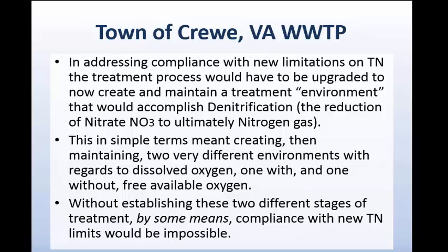We just had to maintain the environment that was already rich in the dissolved oxygen throughout whatever steps we took in attempting to create that new second environment, a denitrification environment. That was going to require us to create and maintain a treatment stage that would now be void of free dissolved oxygen, but that was going to contain the microbial required combined form of oxygen, NO3 or nitrates.